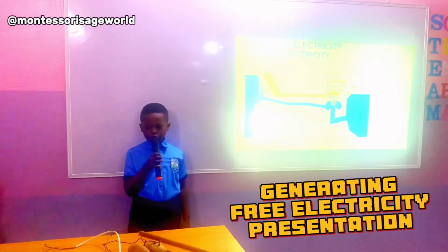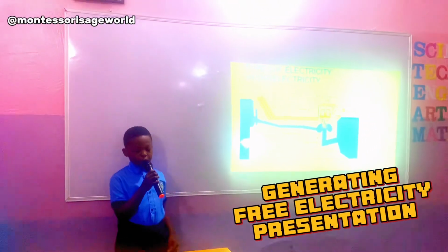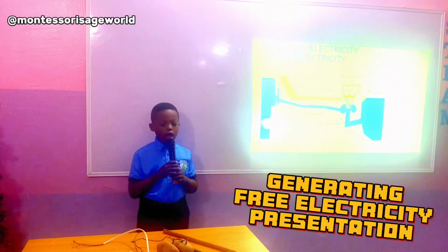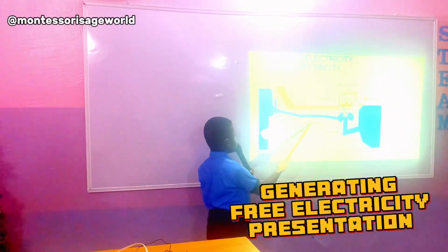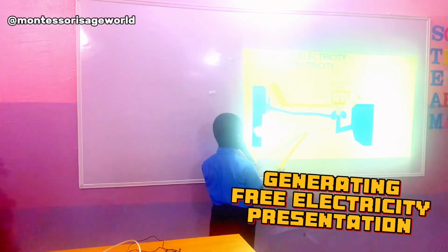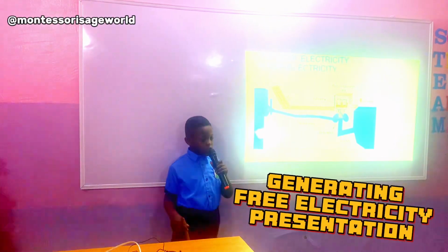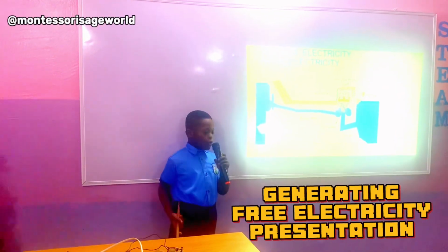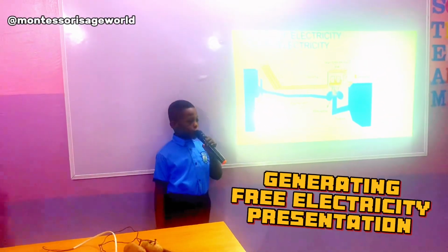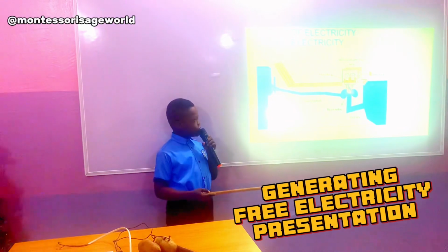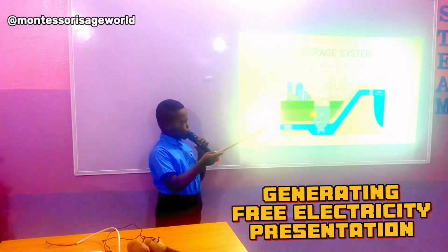Types of electricity. Hydroelectricity. This is using energy from water to generate electricity. At the plant level, water flows through a pipe, also known as a penstock, and then spins the blades in a turbine, which in turn spins a generator that ultimately produces electricity. Most conventional hydroelectric facilities operate this way, such as the run-of-the-river system and pumped storage system.